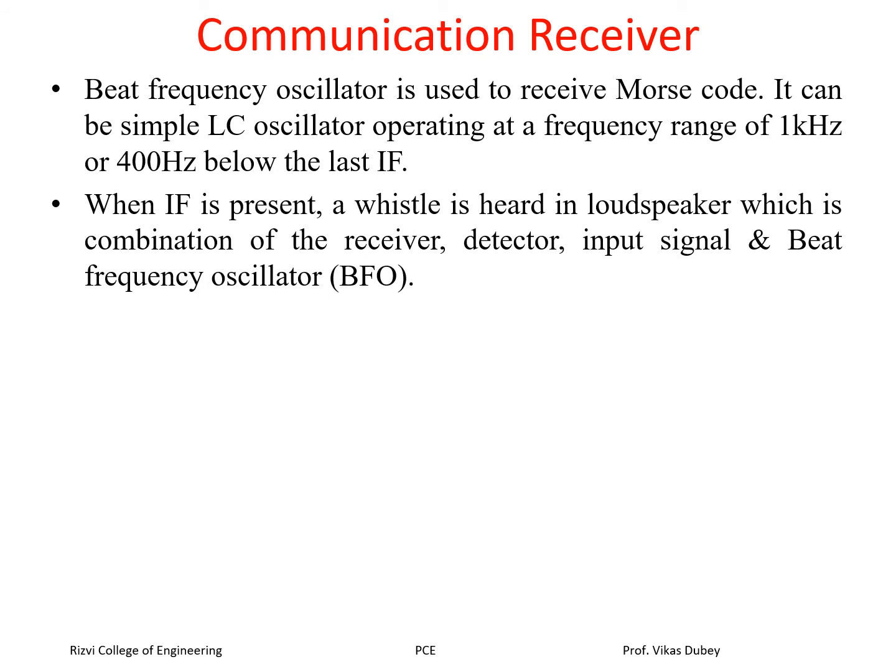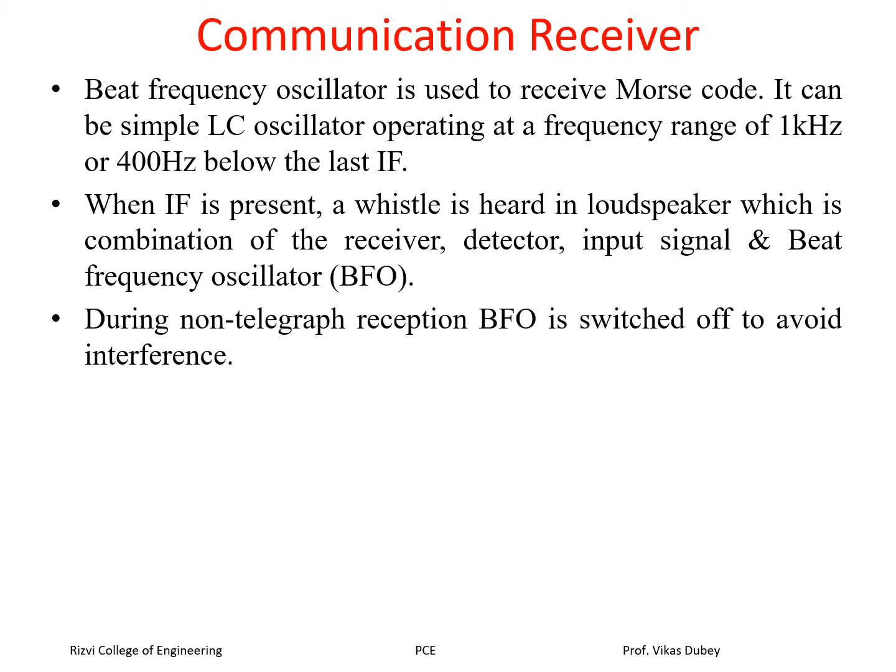Now when the intermediate frequency is present, a whistle is heard in the loudspeaker, which is a combination of the receiver detector input signal and the beat frequency oscillator frequency. During non-telegraph reception, the BFO is switched off to avoid interference.